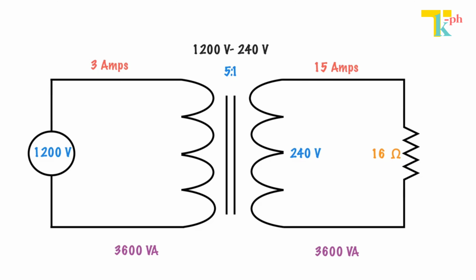In this case, that equals 3 amps, which is what we worked out before when we used the turns ratio. I know it seems like there's an extra step involved, but I just find it way easier to deal with the VA in, VA out rule than trying to remember that I might have to step up or step down my current depending if it's a step up or step down transformer. So again, VA in equals VA out will get you the right answer all of the time, and you don't have to confuse yourself so much with the turns ratio and the current.